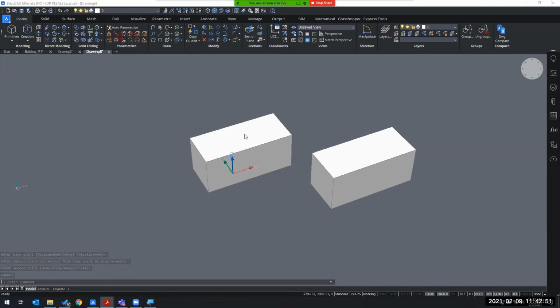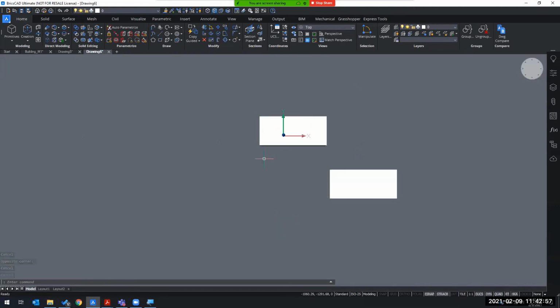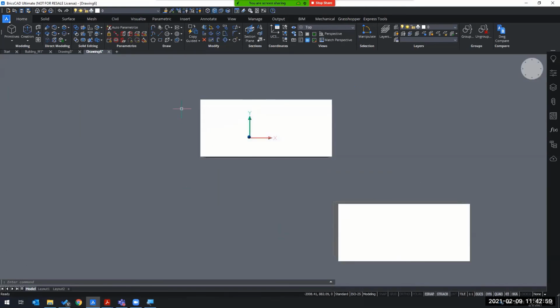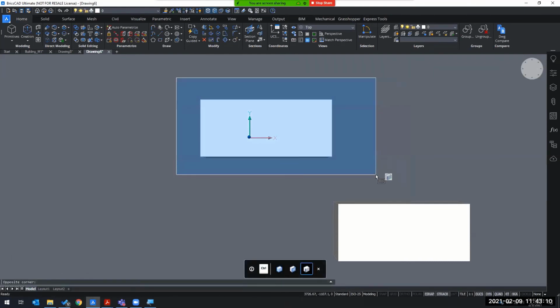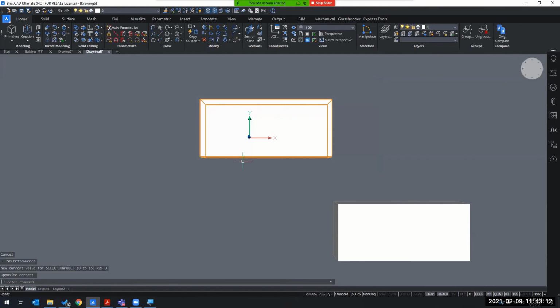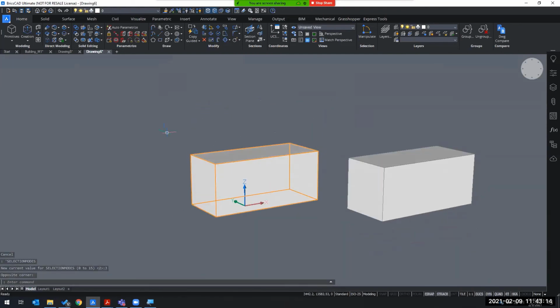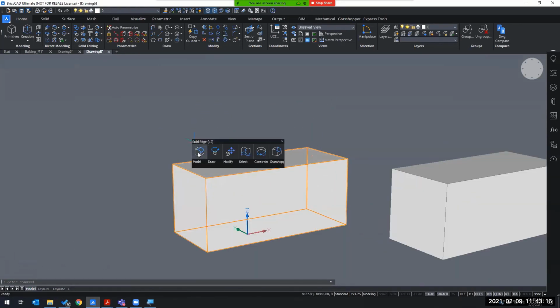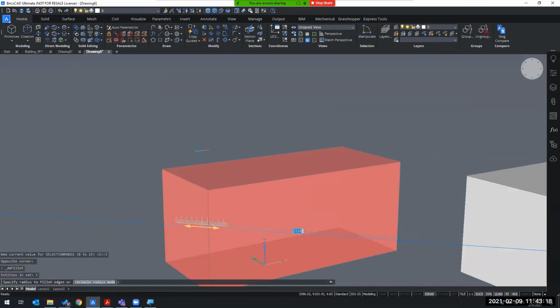Now let's go ahead and check out some manipulations on the edges. So I'm going to maybe enable now the edge. Or actually, I don't even have to. I'm going to use the example of selection and toggle through my selection modes, and now I have all my edges selected. So I can now add a fillet, and let's keep a value of 10.